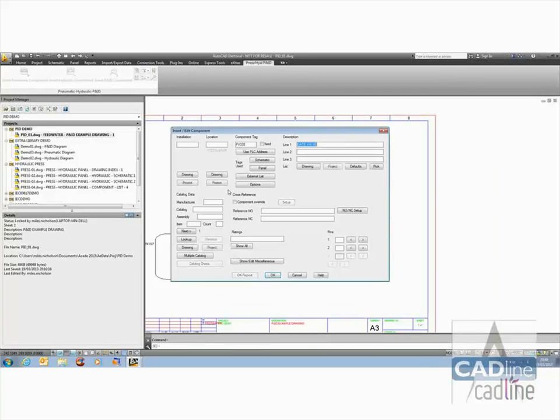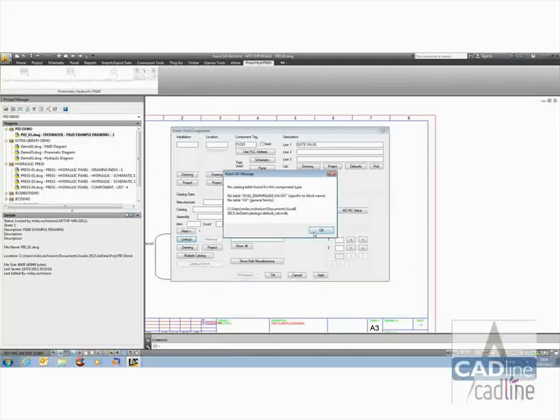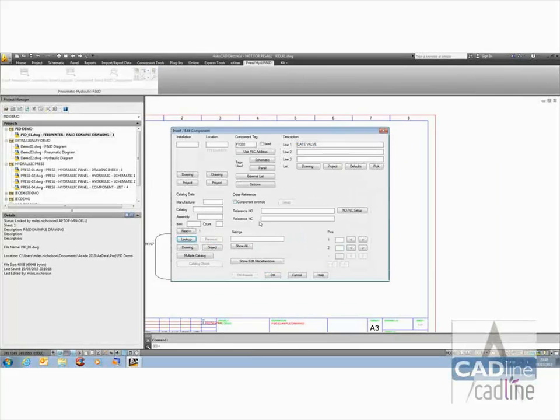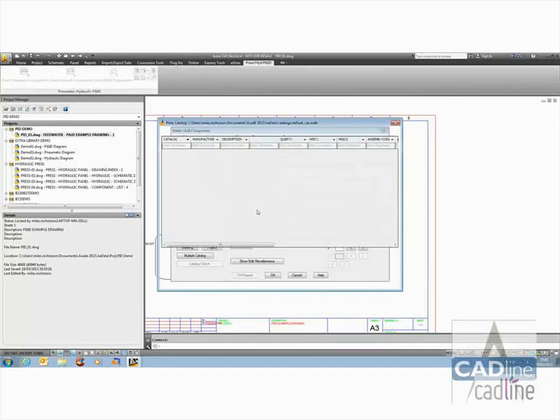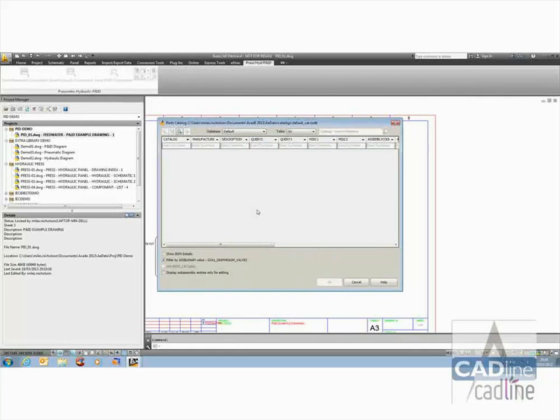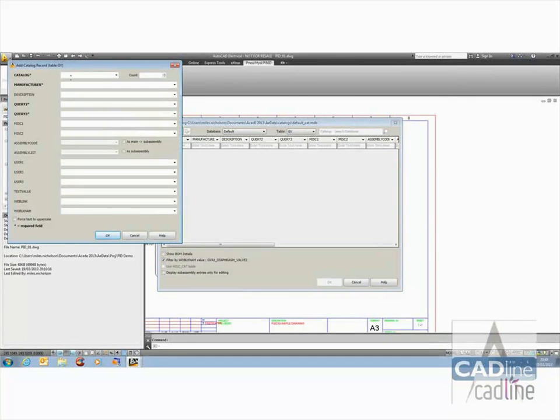Any component we can assign a manufacturer and part to. As a default, AutoCAD Electrical's parts database is predominantly electrical, pneumatic and hydraulic. But we can create new components in the parts database with manufacturer part detail. And this will be information that will fill out into the reports.